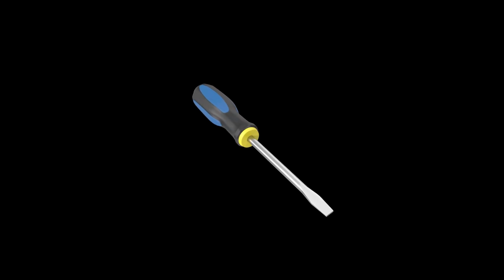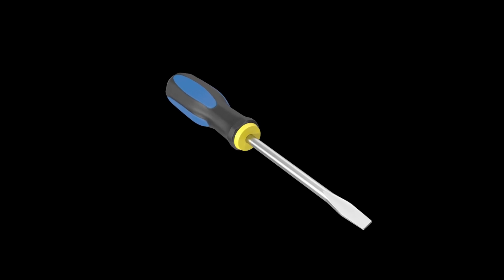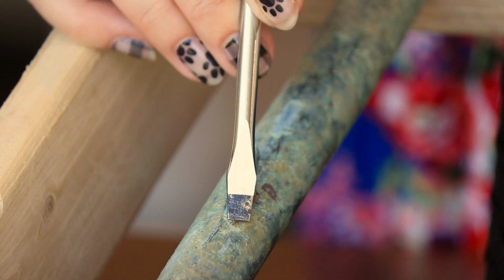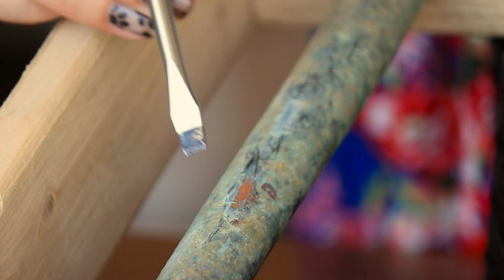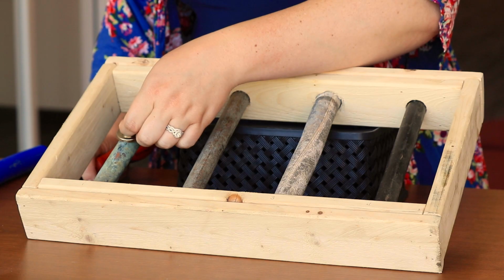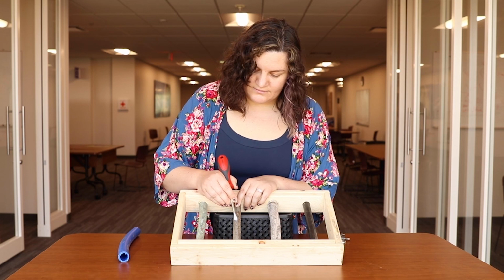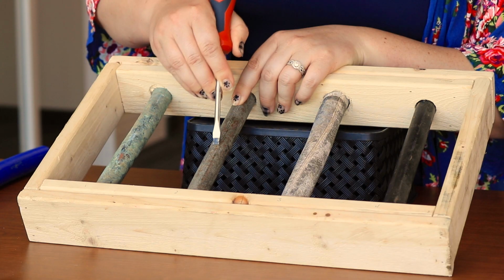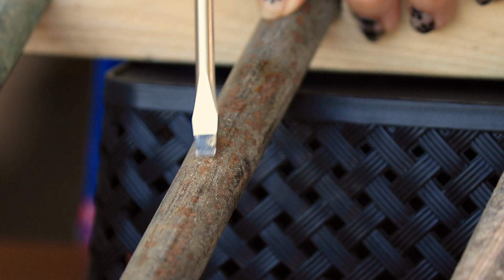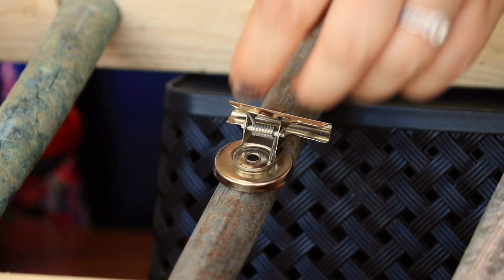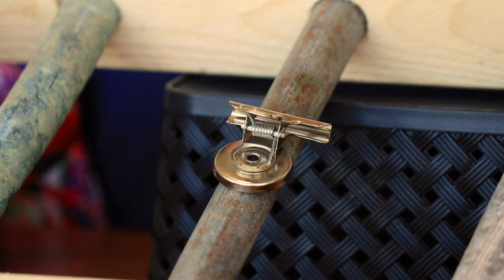Use the flat edge of a screwdriver to scratch the service line in an area before any valves or meters. If the scratched area appears to be copper in color, like a penny, the service line is made of copper. A magnet will not stick to a copper pipe. If the scratched area remains a dull gray color, the service line is made of galvanized steel. A galvanized steel pipe is very hard and not easily scratched. A strong magnet will stick to galvanized steel pipe.